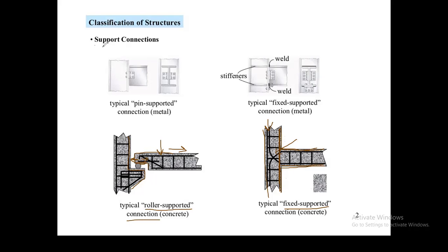So we are talking about the support connections here. Pin supported is there, roller supported is there, then fixed support: in case of a metal connection, that is welding, and in case of concrete, whenever concrete is filled in between the space of the reinforcement bars, these bars are joined together to act as a unit.